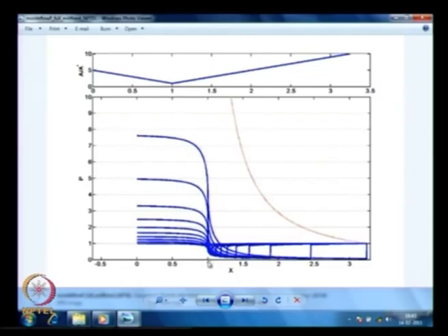If you look at this x equal to 1 location, which is our throat location, the pressure is continuously increasing after it gets choked. In fact, even for some time it will be decreasing, and then it will keep on increasing above that. At this point this is the pressure P star. If you look at that number, from there it will be roughly half. 0.75, half of that is 0.375, it is slightly more than that. So this is my x equal to 1 point. P star is higher, it is above atmosphere here.